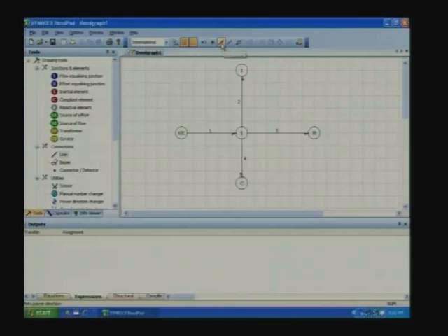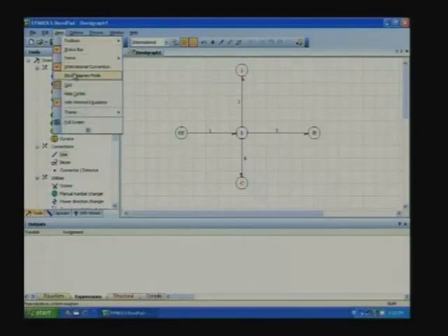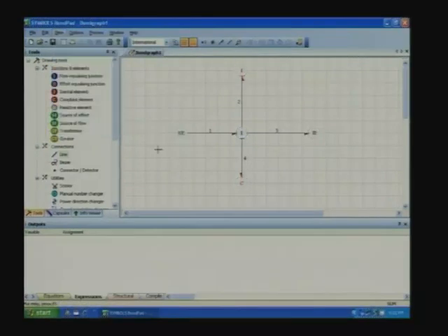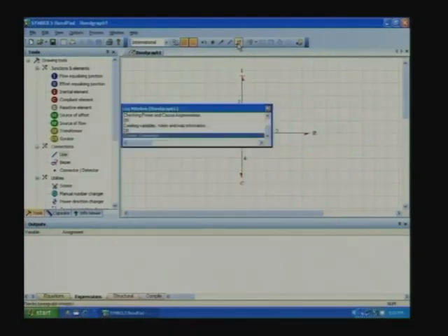After we have connected, we will give the numbers, the power directions, and the causalities. If you cannot see the causalities because the circles are there, we will hide circles. So, you can see the causalities, right? AC is receiving the flow information, I is giving the flow information. So, in one junction the flow information has come, it is distributing in the other bonds, is fine. In any case that needs to be tested. So, check integrity, it says 0 errors, 0 warnings. So, we are fine.